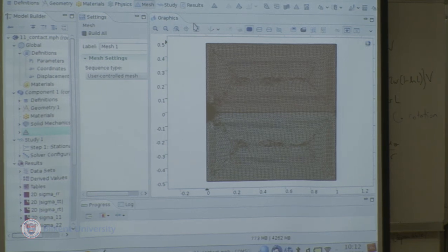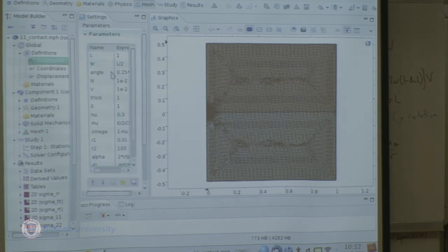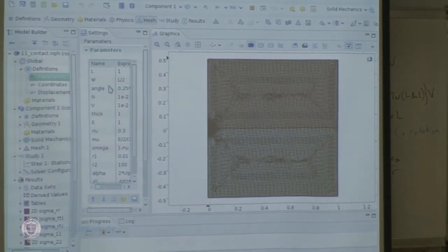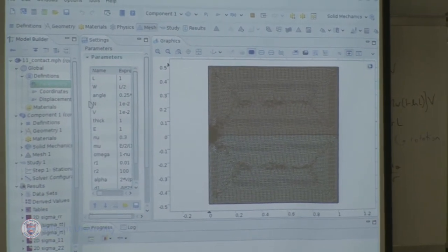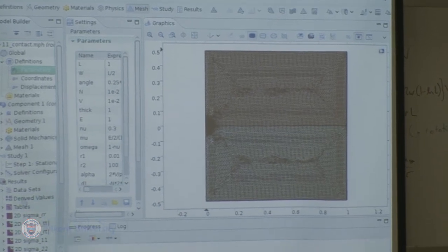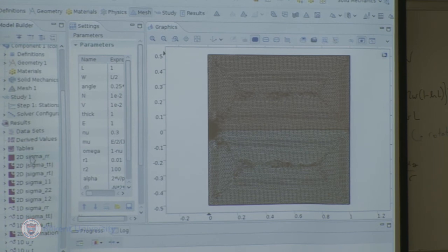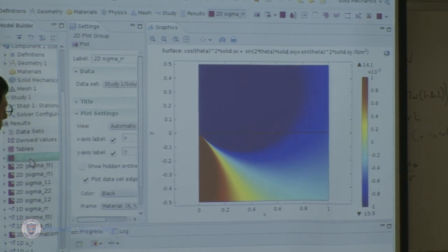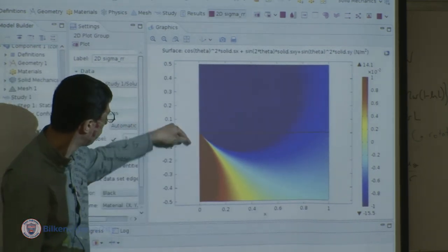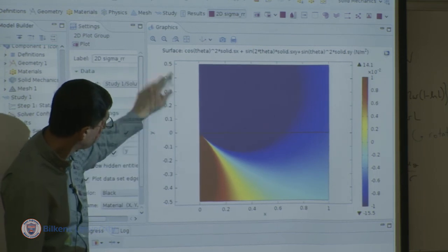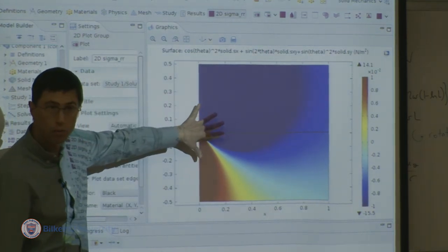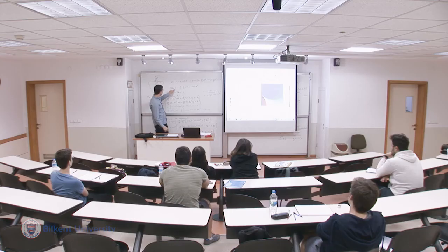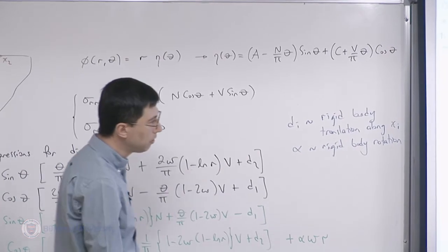So that being the case, presently I have a set of parameters that I have defined. The length of the domain is 1 by 1. And the force is fairly large with respect to this domain size, actually. And let me show you what the solution looks like. Okay, so now I'm going to show you a couple of pictures. Here, for instance, x direction, y direction, normal force, vertical force, and tangential force, sorry. And this is the sigma RR distribution, radial stress distribution. Okay, the radial stress distribution, right? So you see there's an r and theta dependence, and it looks fairly complex.